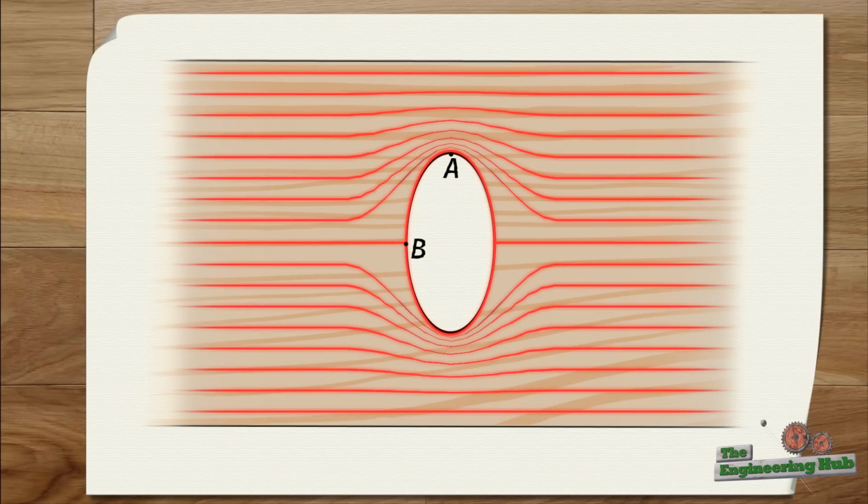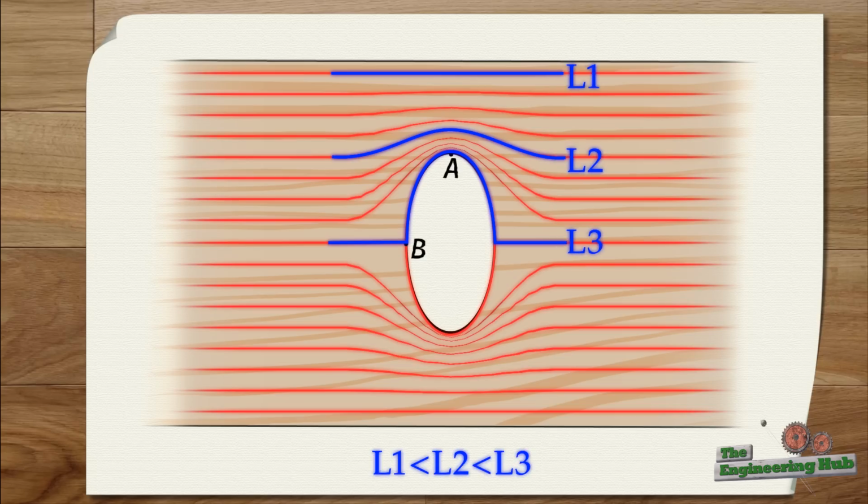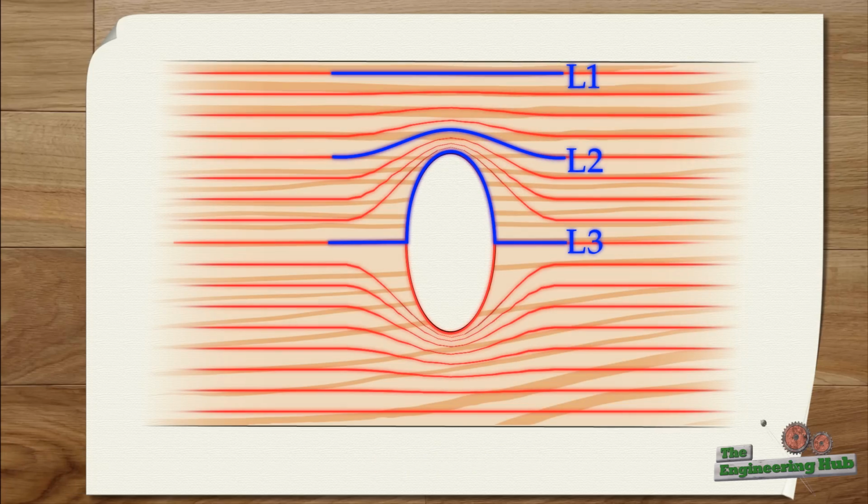The reason why the velocity of the fluid is high at point A is because we have extended the streamlines of the fluid particles traveling near the middle of the beam, so the particles have to speed up around the hole in order for continuity to be maintained. By continuity, I mean the amount of fluid entering the bar has to be the same as the amount of fluid exiting the bar, meaning the particles from different parts of the bar have to enter and exit at the same time, so that there is no fluid backing up inside the bar. So, the question now becomes: how can we reduce the length of the streamlines around the hole so that the particles do not need to speed up as much?